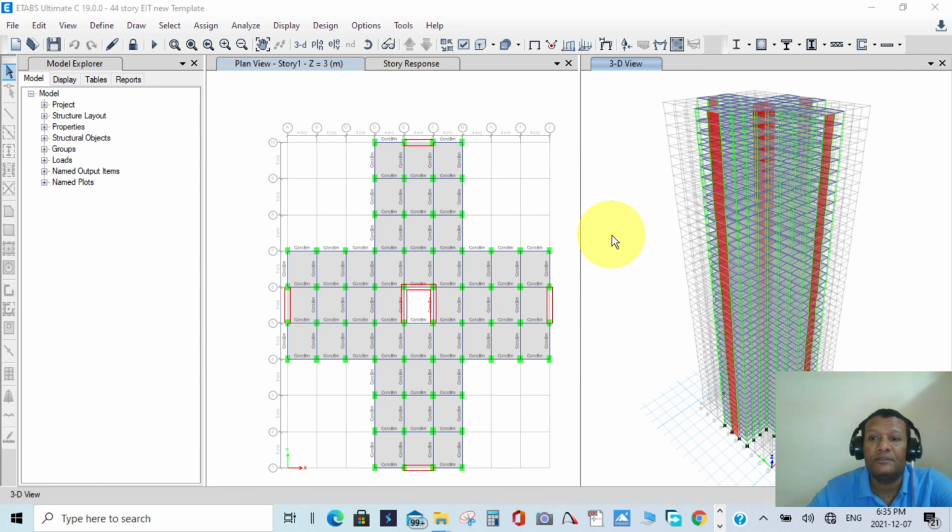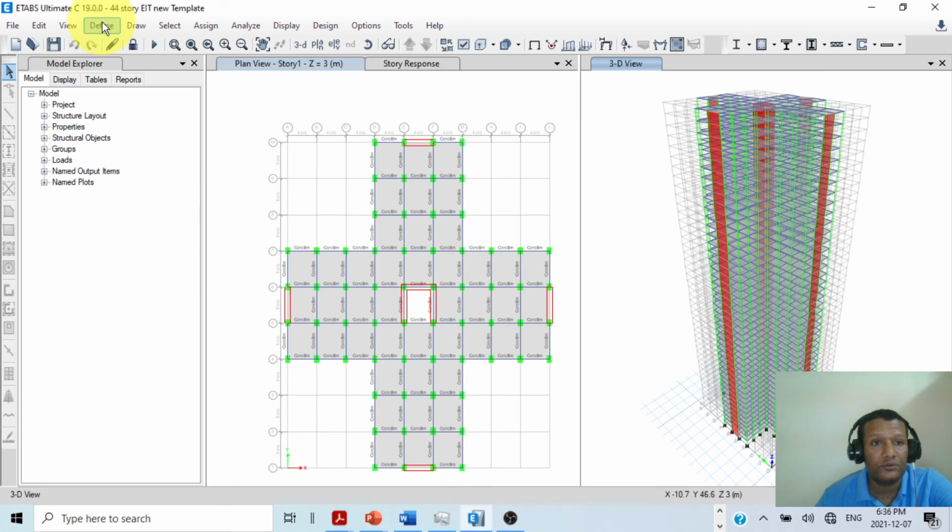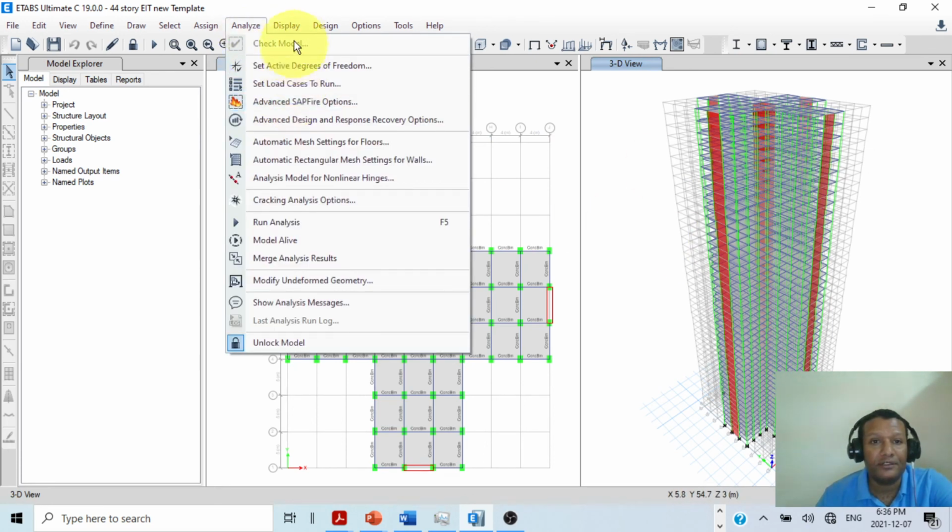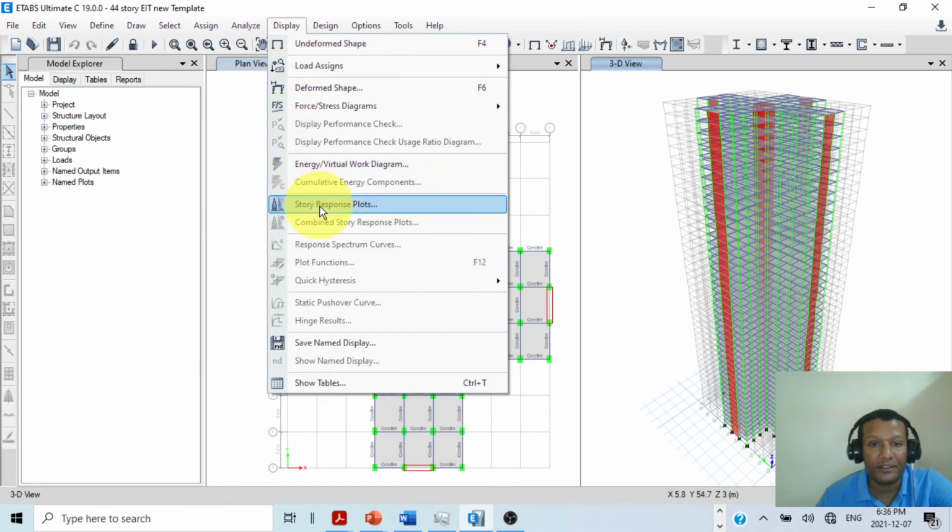And at the end of the day, for our project, for our research, I made the analysis with the Ethiopian building code standard, and I defined the response spectrum of Ethiopia as per type 1 and soil type B and the gravity 0.1 g condition, and we found the global responses for comparison.